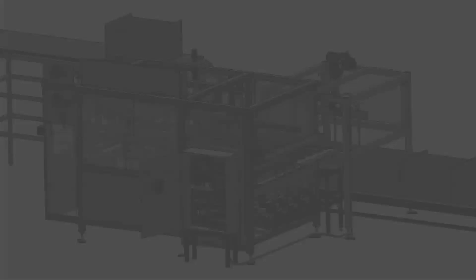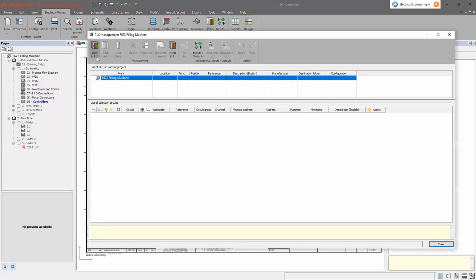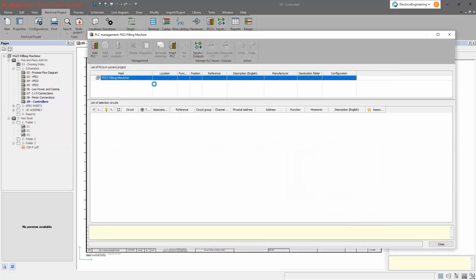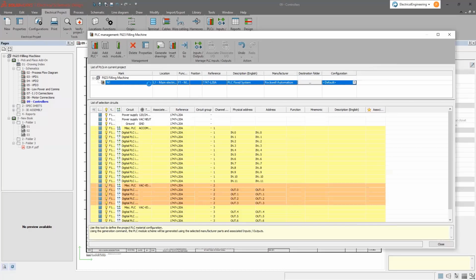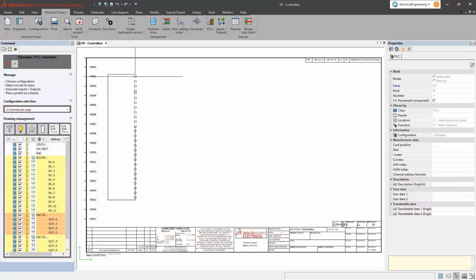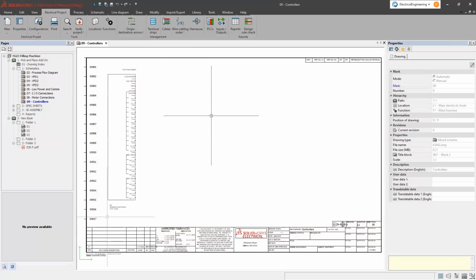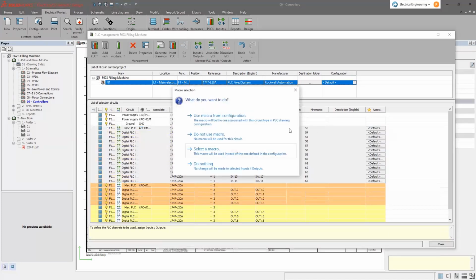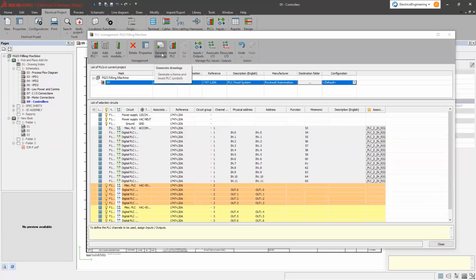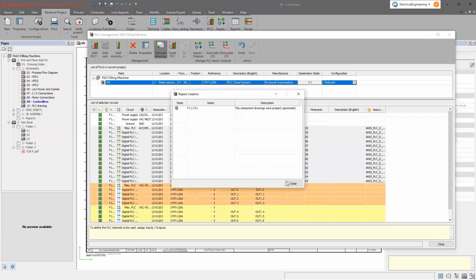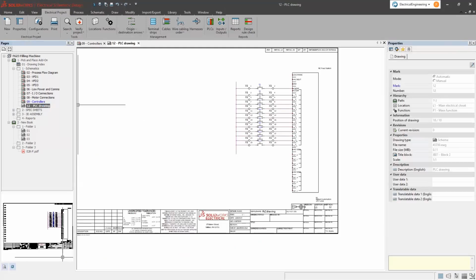All right, let's get back to the automation equipment and dealing with those proximity sensors. With the addition of these new sensors, we should also consider updating our PLCs. Electrical Schematic Designer also provides intelligent PLC management tools. After deciding on the appropriate manufacturer part, I'll select Insert PLC and generate the schematic symbol automatically. I can even go as far as defining a specific macro for each I/O port within the PLC. Now, when I insert the PLC, it will also include each I/O's associated circuit. This function provides me with a great starting point for my design and requires a lot less manual entry.